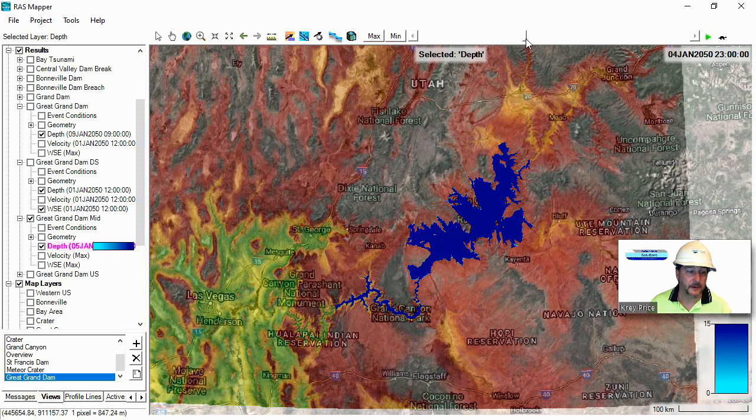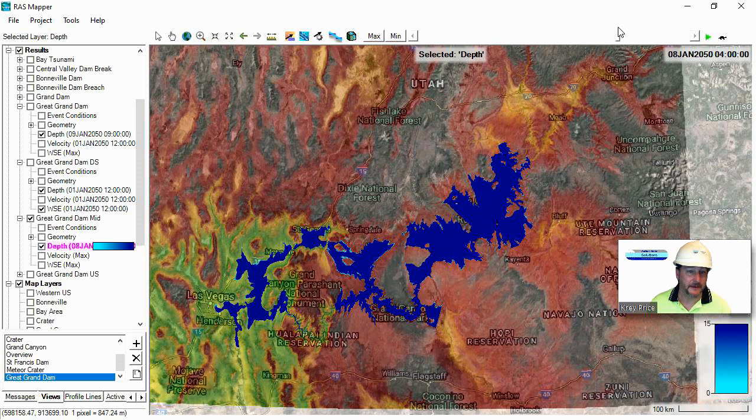It starts heading down the Grand Canyon. Now I'm blocked all the way to the canyon walls here by the terrain. Again, you've got to make sure you have break lines along that narrow canyon or narrow dam wall. But if you have a look at that, it's actually sending some flow back up through the Grand Canyon the other way. So we have successfully dried out this area, if that's a success. But again, that's just something we can play around with in the terrain modification tools.